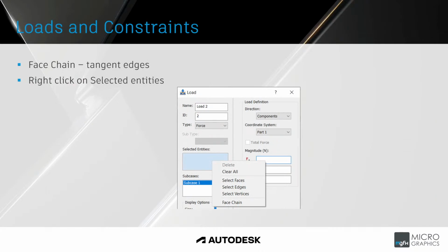Okay. One thing that you can also do over here is when selecting face edge vertices. Normally, we start our load, we start our constraint, and then we start clicking, and actually to select the points, I need to select the line, so it's right click, select other, and then you start to cycle through the different options that you've got over there.